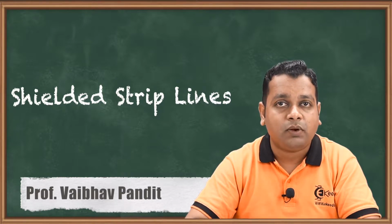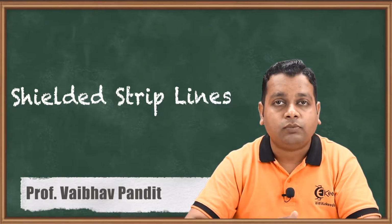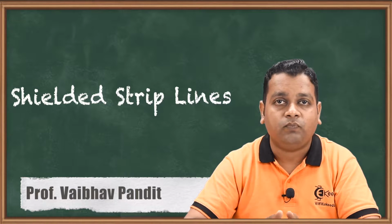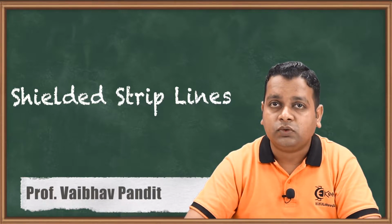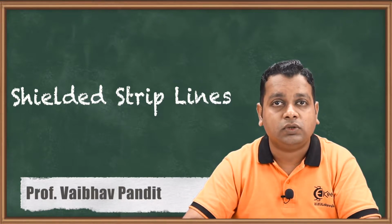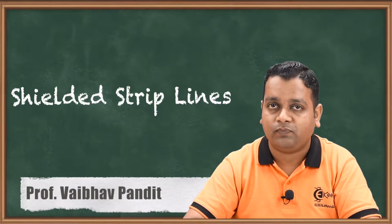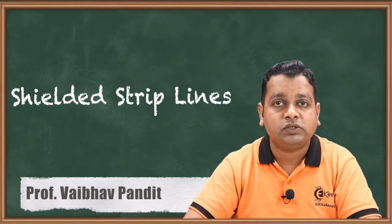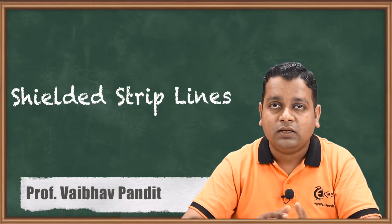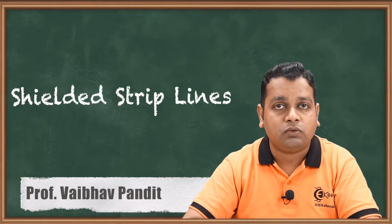called strip lines and its modified form after removal of a ground plane, that is microstrips. After the introduction and the comparison of the two, we have solved selected problems on the strip lines and microstrip lines. We have derived the characteristic impedance and some related parameters to the performance of this transmission line also. The various forms of strip lines we dealt with, like the parallel strip line and, in the previous topic, the coplanar strip line. So we have solved one problem on them also.